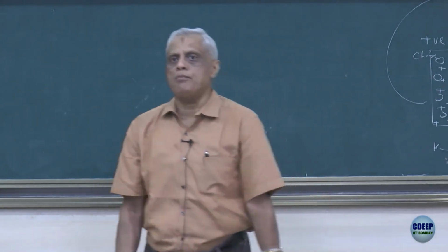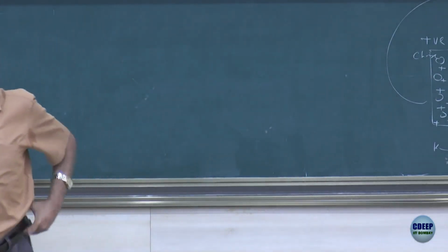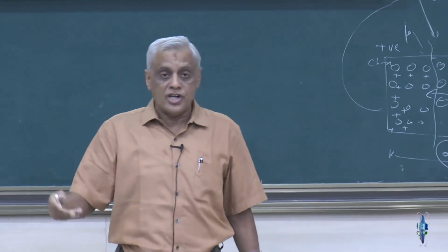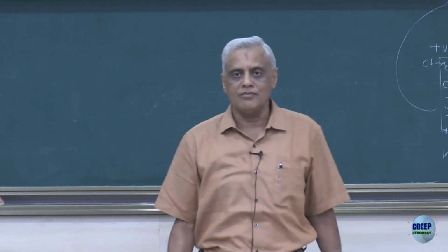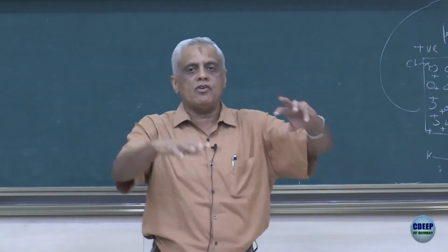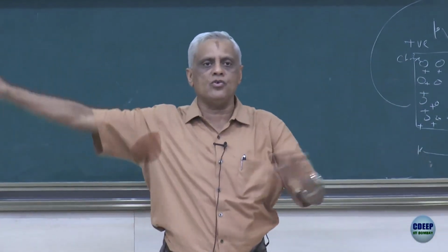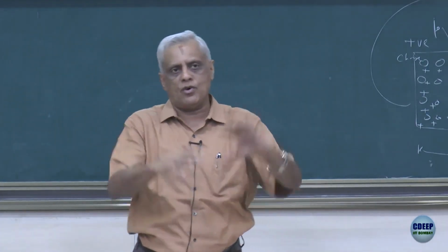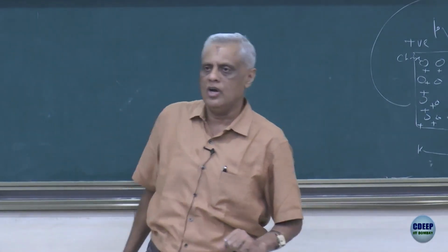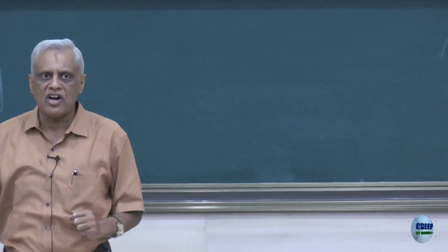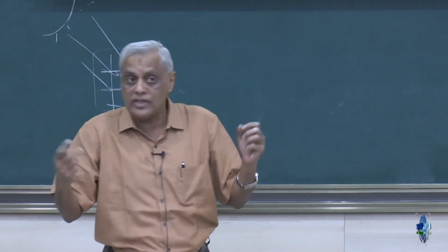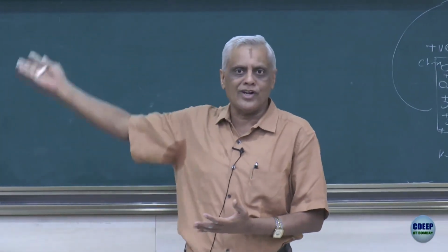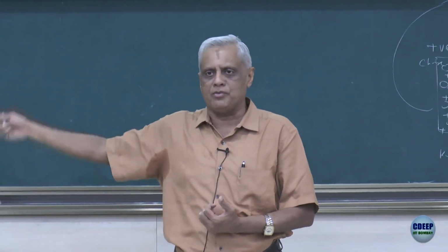So a very big component of this course, particularly the first few lectures, would actually go in explaining to you the various switching devices which are there at our disposal. So there was a time people were using mercury arc rectifiers because there were no semiconductors. These mercury arc rectifiers or vapor rectifiers, there were several variations, they were not that reliable. Though they were able to handle very high power, they were not that reliable. Plus they were not able to do all these other four configurations that we have seen. They could not do those kinds of operations.